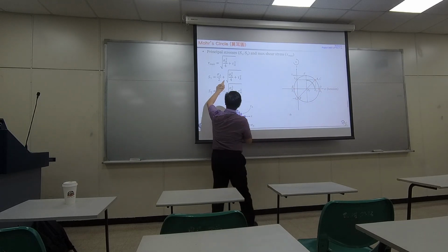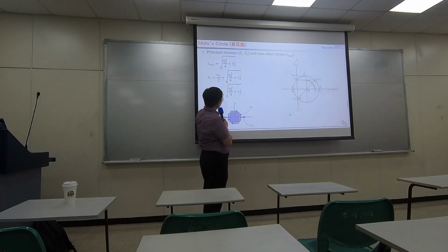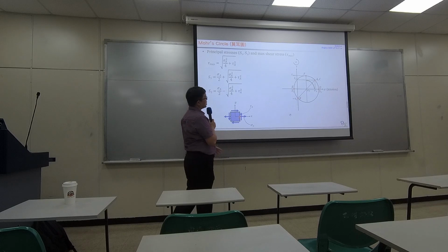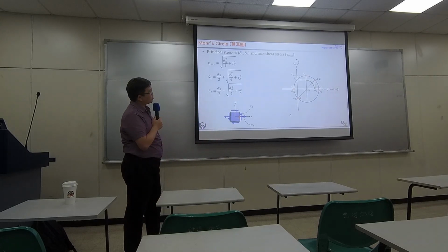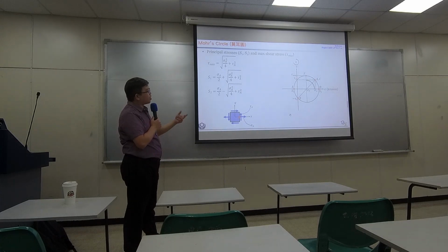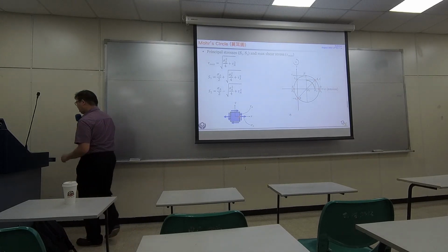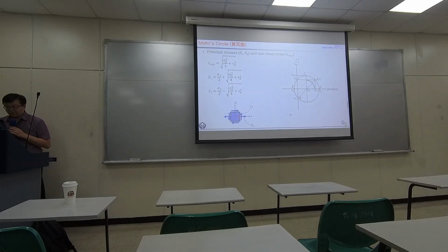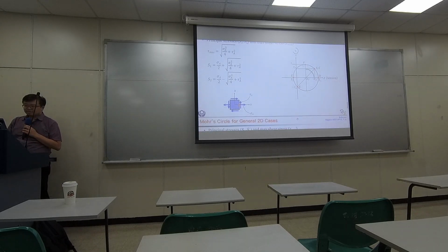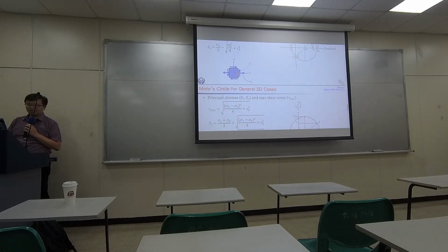So here is adding the radius, and here is minus the radius. That's how you can get the first principal stress or the second. Okay, so if you compute the radius, you can easily get the first and second principal stresses. Okay? Any questions? If you have learned this, this is super easy for you.